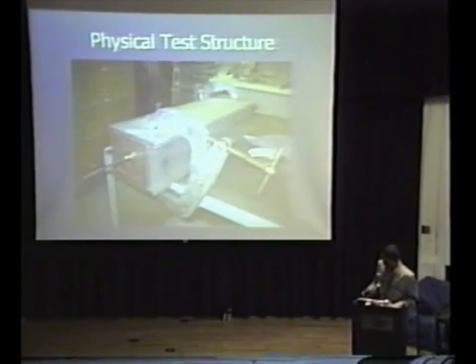The next picture is my waveguide with the top on, with the single patch element inside being fed by the coaxial line. I clamped together the waveguide with the clamps, and it worked out well because I could vary the tolerance of the dimensions of the waveguide.